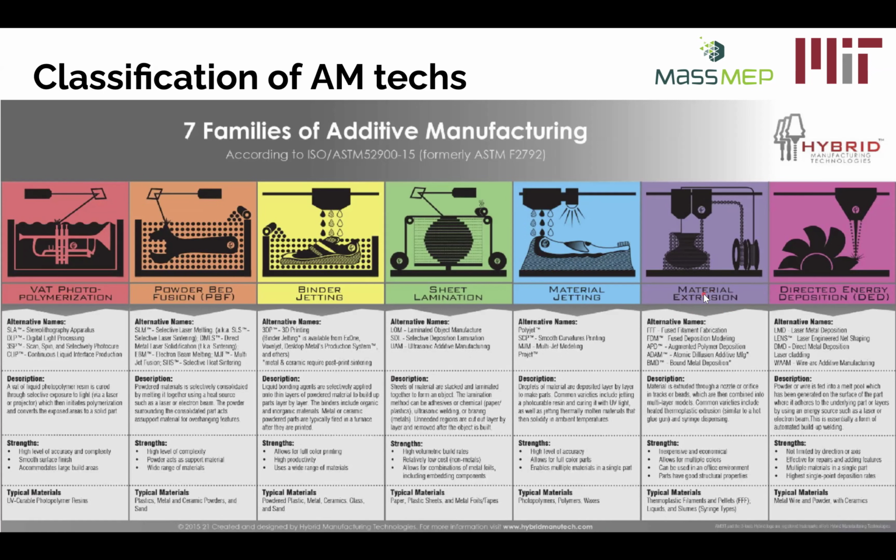But it's because the strength of the material is not isotropic, meaning it's not of equal strength in all directions, but it's a little bit weak where the layers overlap with one another. So instead, the process that they use is the one all the way on the left, that photopolymerization, because that can make fully cross-linked elastomeric polymer components, meaning that they have fairly isotropic mechanical properties, and we can use them in applications where, for example, if you're playing football, you're taking hits in all different directions, and we want to keep you protected in all different directions.